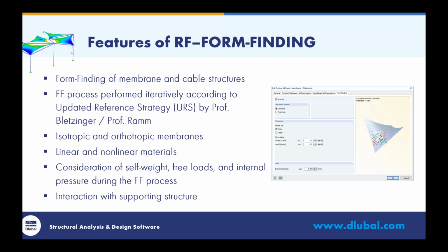So when we take a look at RF Form Finding, this module is actually embedded within RFEM. This allows us to perform the form finding procedure of both membrane and cable structures. This process is performed iteratively according to the updated reference strategy by Professor Bletzinger and Professor Rahm. We can consider both isotropic and orthotropic membranes, which we'll actually see an example of both of those today. We can also consider linear and nonlinear materials.